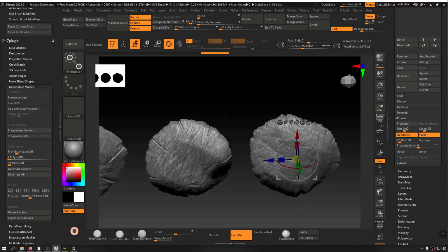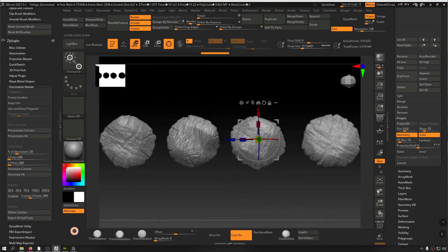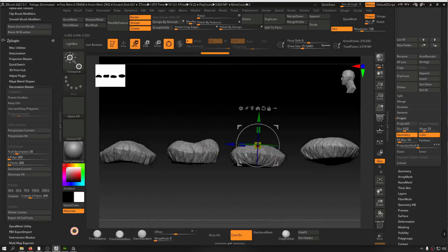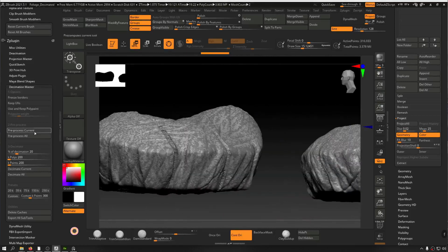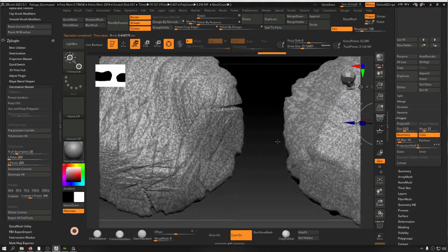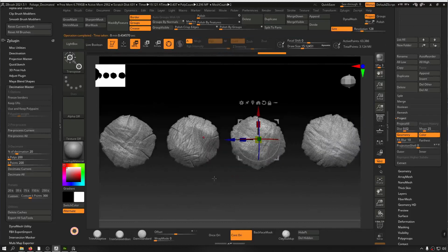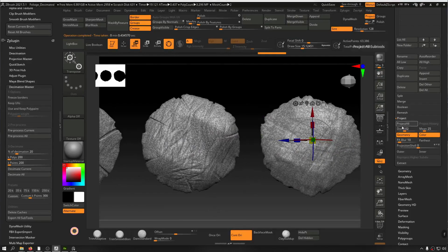And it makes sure that there's no room between the high poly and low poly. You can already see that. Okay, and now let's decimate again. I'm going to go much more down from this because, as I said, we're going to copy this a lot of times, and we're going to have a harder time if the polygon count is so high. So let's take this and project again.